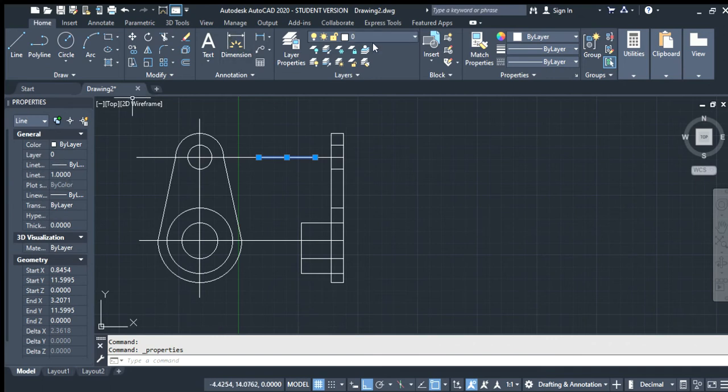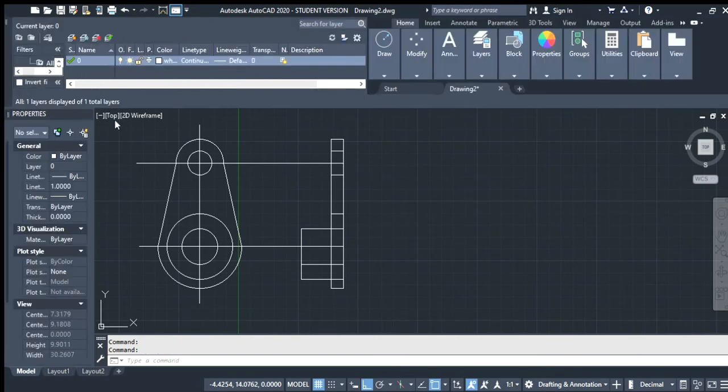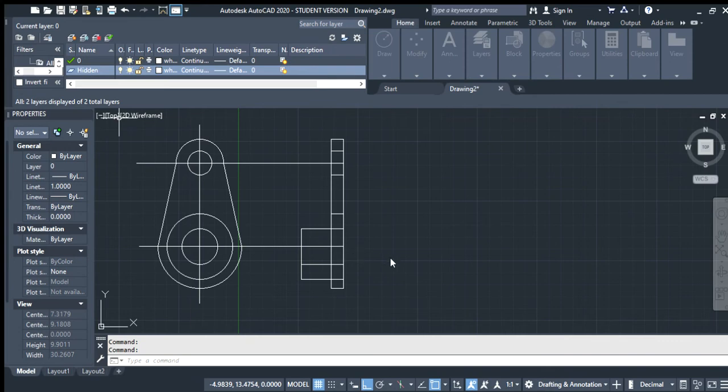You're going to go ahead and go back up to layer properties. You're going to right click and add new layer, and then you write that as hidden. Name that hidden. Click line type and go down to load. And it tells you we're going to look for hidden 2-5, and hidden 2 is right here. Hit OK. Again, if you can't see the pop-ups, I apologize. The program I'm using to record sometimes only allows me to record one application, and it doesn't recognize pop-ups. So you select hidden 2, and if you're following my instructions, you'll see this. Go ahead and hit OK, and up here you'll see it'll change to hidden 2.